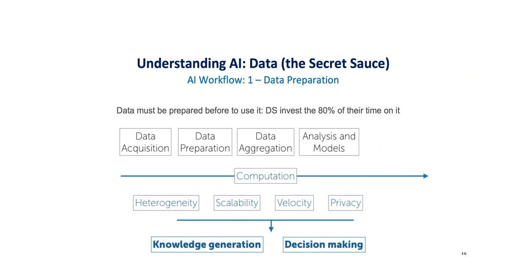What happens, for example, imagine this case: you want to apply AI in real time in your manufacturing process. You have a reactor, and you have a measurement of pH at this moment, density later, humidity one second later, the agitator speed one second later. How can we do big data, how can we do AI with this data? Because we cannot put it together in the same line. We need to create this kind of time alignment. That must be foreseen and integrated in the strategy.